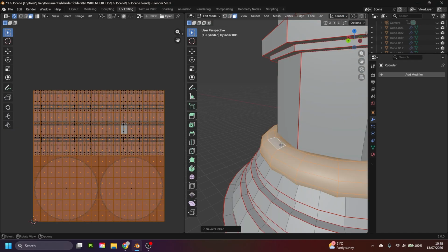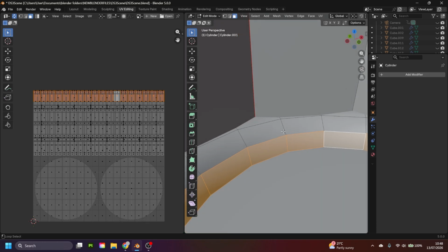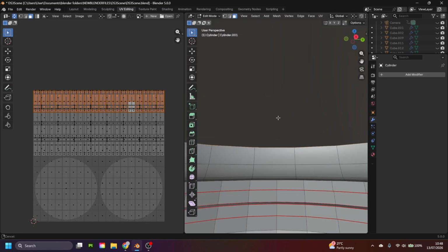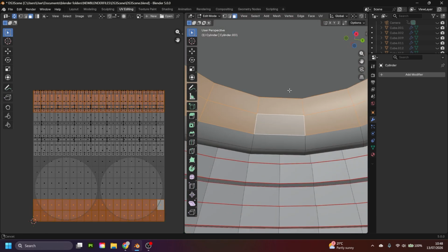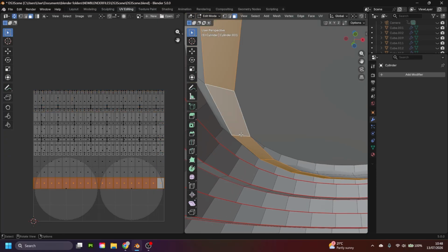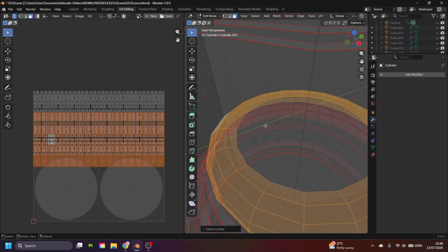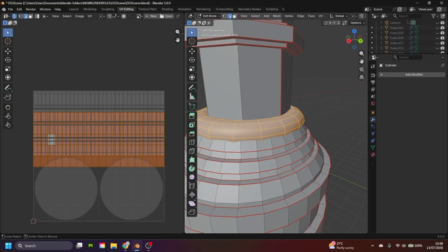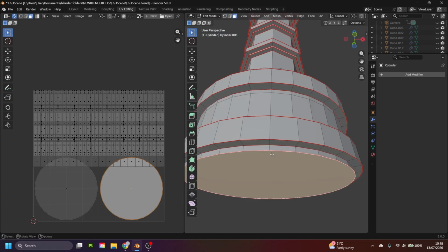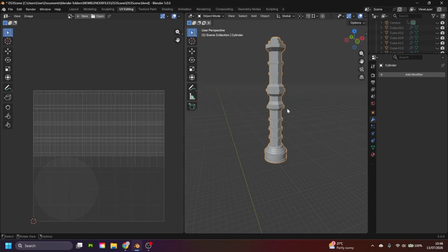With this cylinder here, or not a cylinder, the ring, I'm just going to remove these faces because you can't even see them in the final render anyway, so they're hidden inside the other objects. And go all the way down here, delete the faces, delete this one as well, even this one along the outside. And now this whole object is going to be a lot easier to unwrap. I actually only need to add the seam just back here. Also, to save space, just going to delete the bottom face. Won't be able to see it anyway. I think generally that's okay.